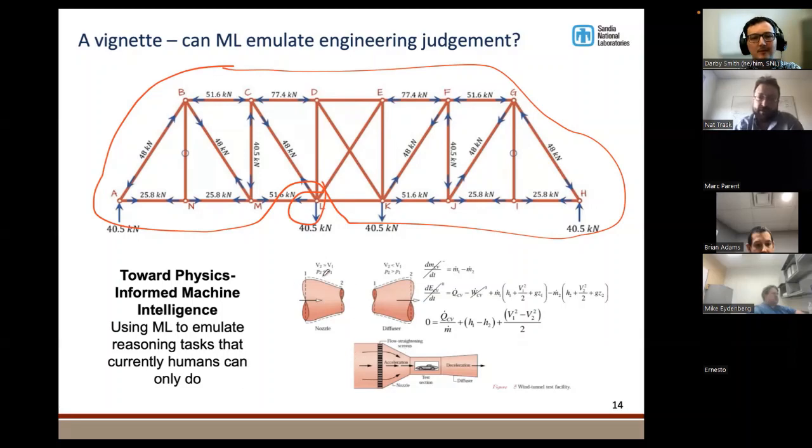And so the same thing sort of happens all over fluid mechanics, where people will strategically draw what's called a control volume, and you'll say, okay, I want the sum of the fluxes in and out of this subdomain to be balanced, but you'll strategically draw that control volume in such a way that you get a simplified but informative analysis, right? So that you can do a lot of stuff with pencil and paper.